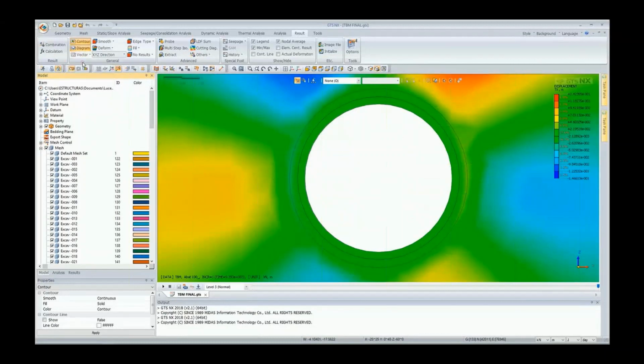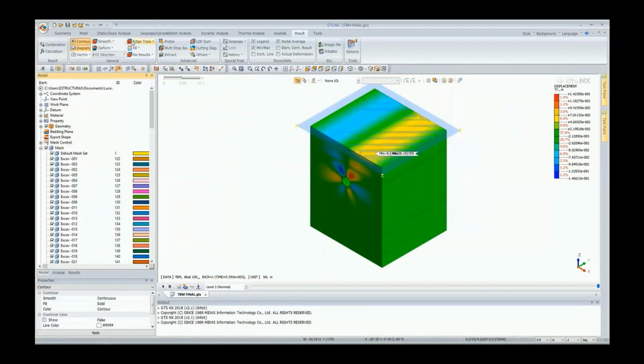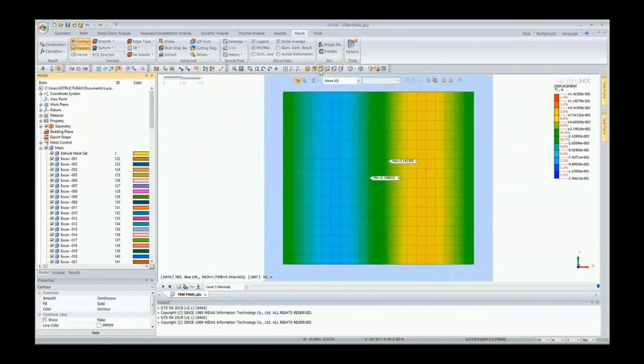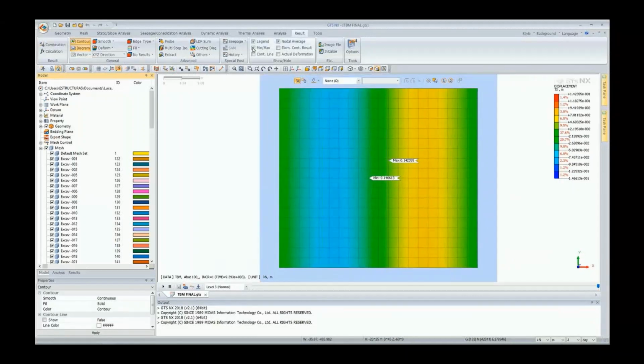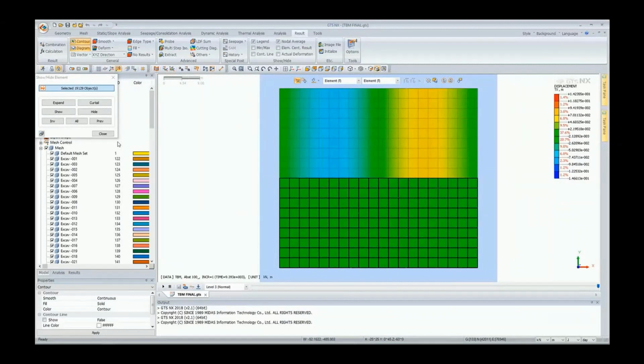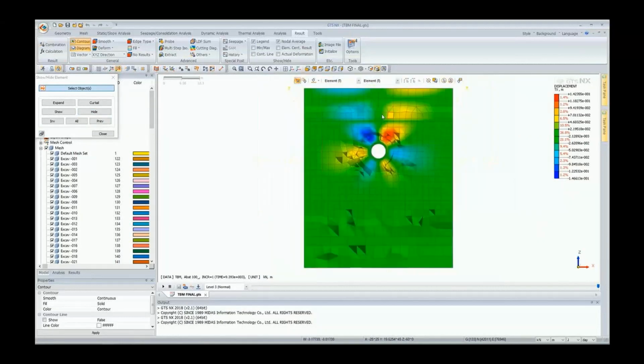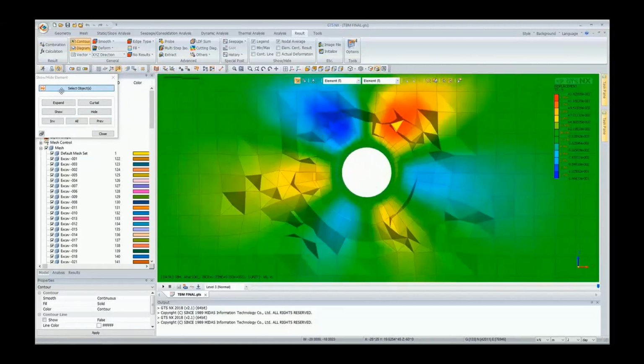So now I'm going to go back and activate the rest of the geometries or the mesh sets, and I'm going to hide the vectors. And I'm going to make basically an extraction of data, and to do that, I want to select what's happening in the middle of the excavation. I do my top view, and I'm going to hide half of the model elements so that I can then extract the results directly from sections that are inside.